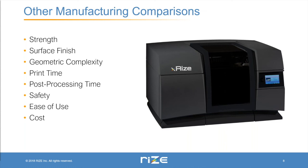Another question is safety. This often comes down to the materials involved. Photopolymer resins tend to be fairly chemically hazardous, so you'll have to be careful when working with those. Powder bed fusion can also be a bit dangerous due to the possibility of catching fire and even explosions due to aerosolized powder.